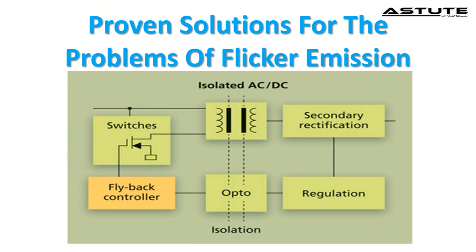To remove or minimize the flicker noise from the device, the following tricks are very important. Capacitance should be added to the output of the driver to filter out the AC ripple component. Some types of ballasts can reduce flicker considerably. Use filtering. Use of isolation transformers is very effective to stop the flicker noise from transferring onto the power line.